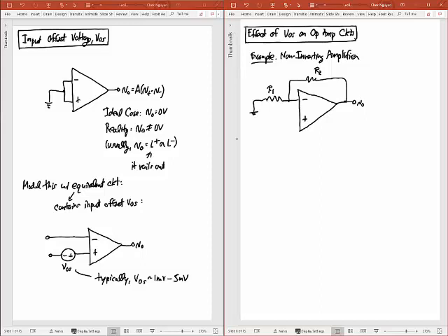Okay, so say I grounded that plus terminal, but if it were an actual op-amp that has an offset voltage, I would have to stick in this. Right? So now that I stick in that VOS, I have modeled the offset voltage non-ideality of this op-amp.